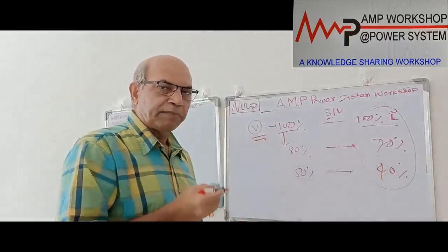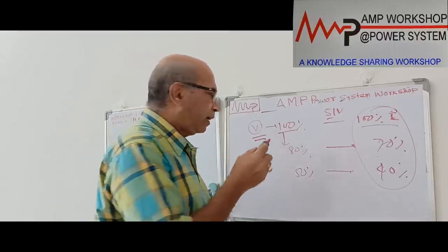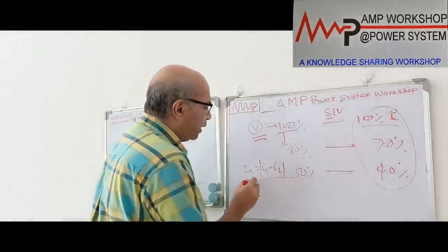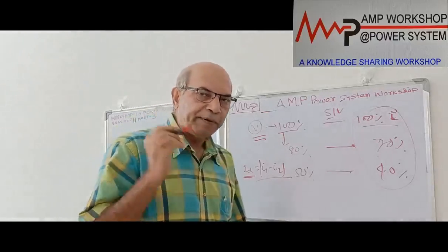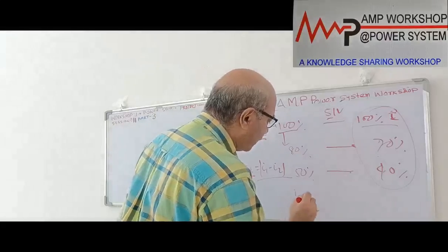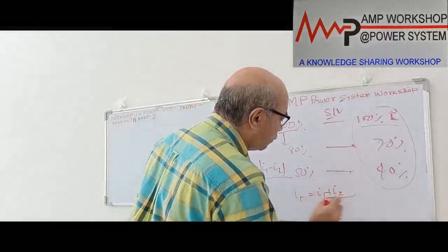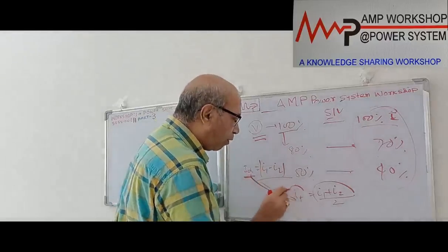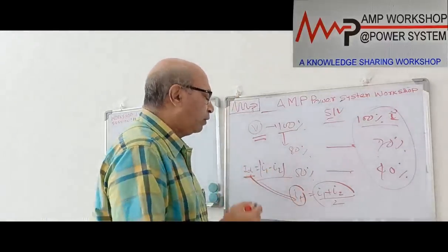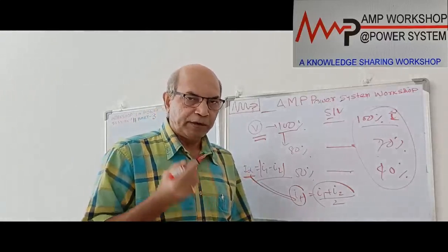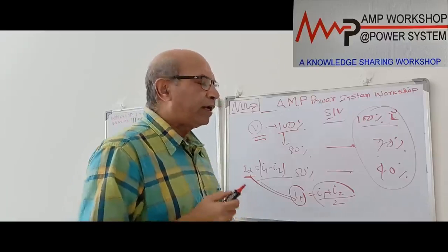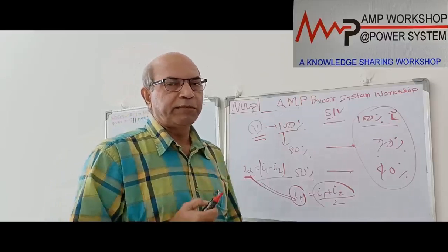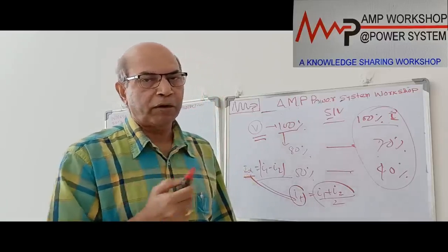So in the case of differential bias busbar differential protection, if the relay operating current ID, which was shown equal to the modulus of I1 minus I2, if we can make this ID value dependent on this fault current IF, that is equal to (I1 plus I2) by 2, if we can make these two interrelated, that means the moment fault current increases, the differential current also increases, and the relay operating characteristic moves up. If we can make this type of arrangement, then this relay will not be susceptible to this CT mismatch or the CT saturation. It will be better than the normal conventional relay.